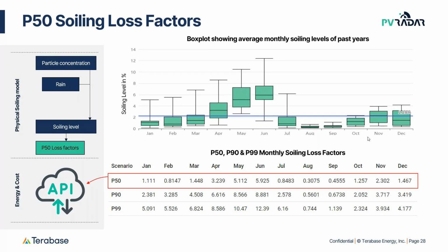But if you're unlucky, you might have measured in just that 1 year where in June, and maybe even May, it shows very low soiling. So you might be underestimating the soiling losses. Or the other way around, you just happen to measure in a year where it's very dry and there's a lot of dust in the atmosphere, therefore overestimating the soiling losses. Through this historical analysis, we're able to get a good average value and also account for the year-on-year variation.